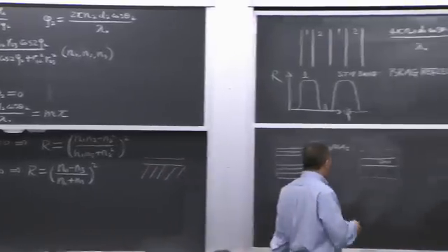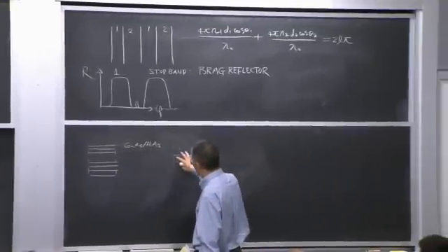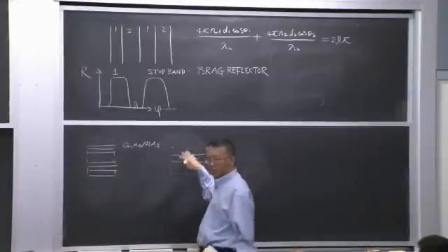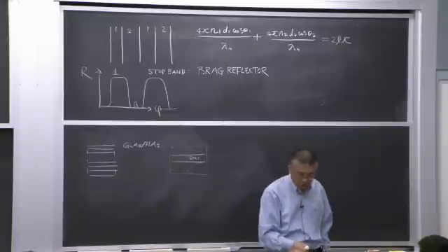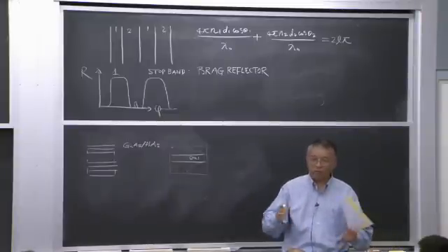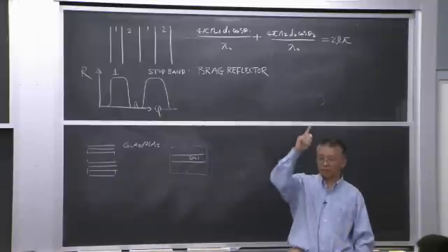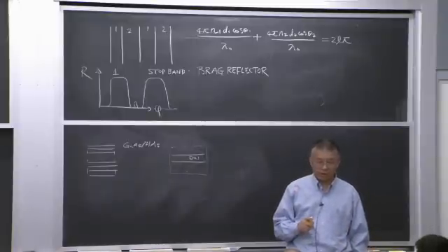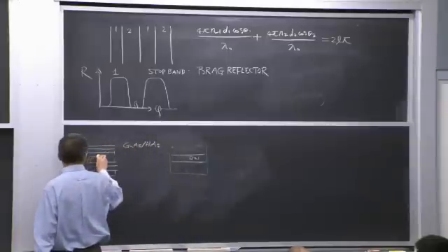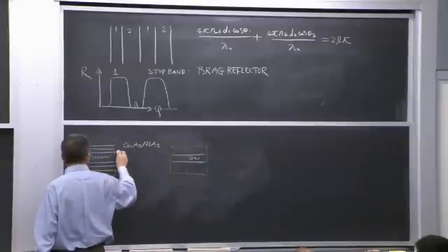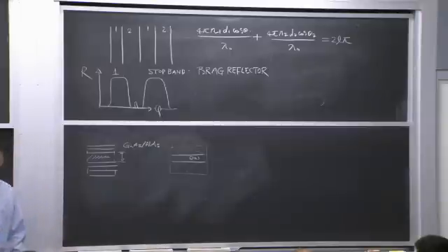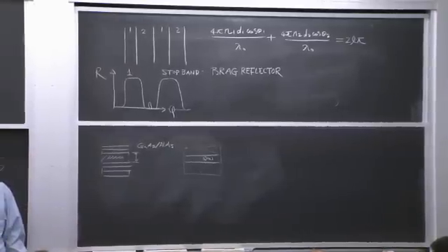So they need a long distance to amplify it. But people don't like this configuration because you have to cleave it, and the light comes from the edge. People spend a lot of time trying to make the light come perpendicular to the surface. In that case, this is the quantum well region, and they have to make this a certain thickness, half wavelength or full wavelength.